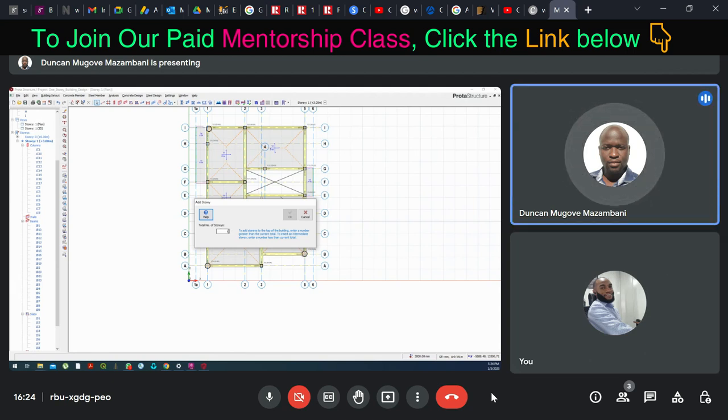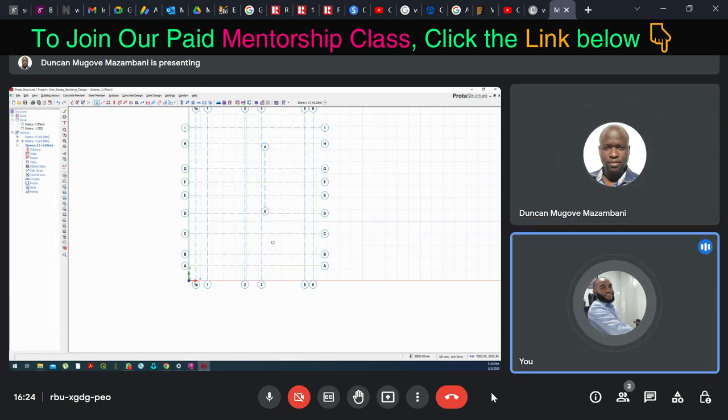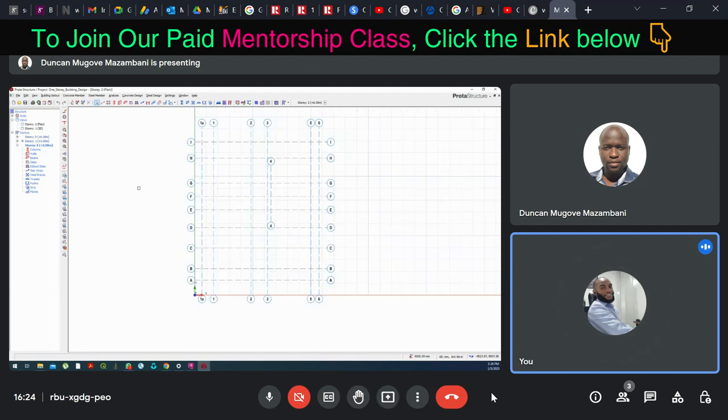Okay. So total number of stories is two. Then click on OK. Then click on yes. Okay, so we now have our story two active. So we now have to go and import those beams into this story two.